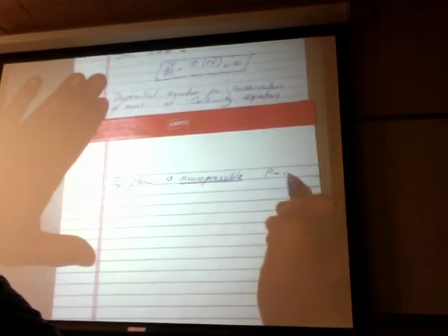That density is a constant, or can be considered a constant. Now, for a flow to be incompressible, the fluid doesn't have to be incompressible. We're getting into the details of the physics here, not into the math. But an incompressible fluid, such as a liquid, for example water, is always an incompressible flow. Water always flows as an incompressible flow because it is an incompressible fluid.